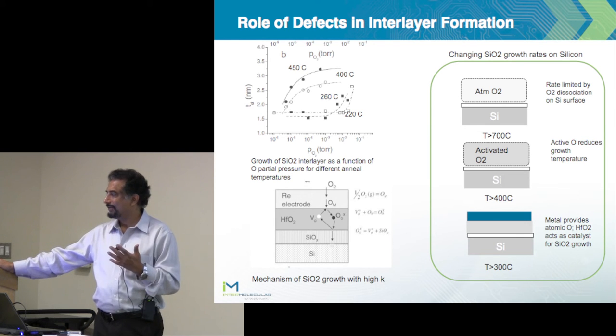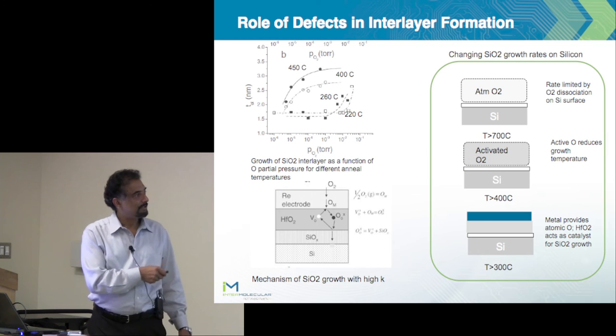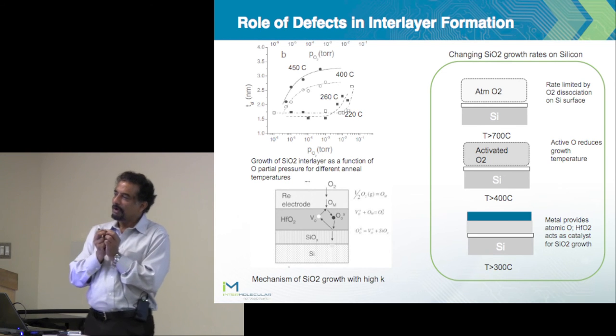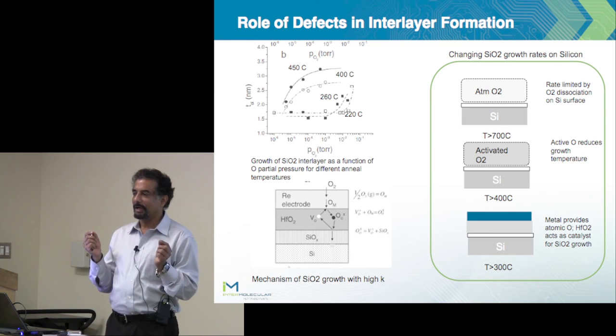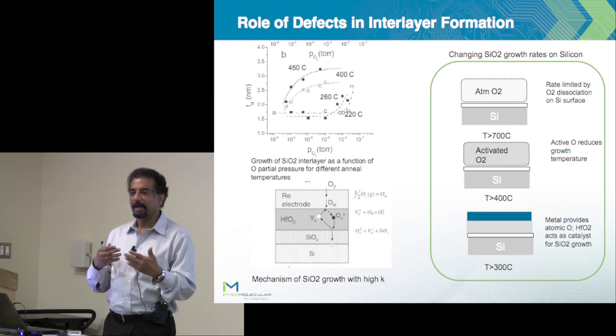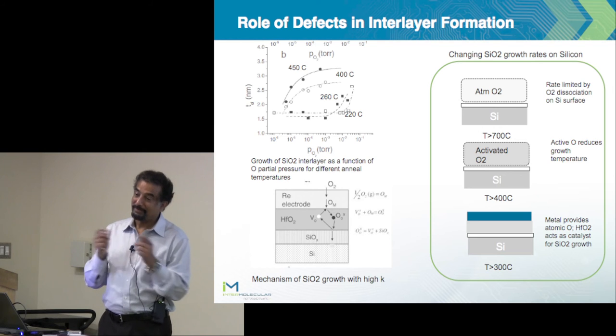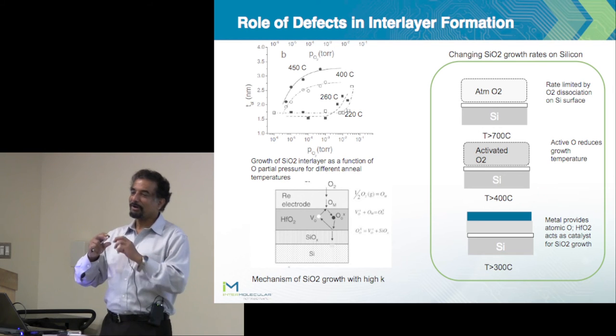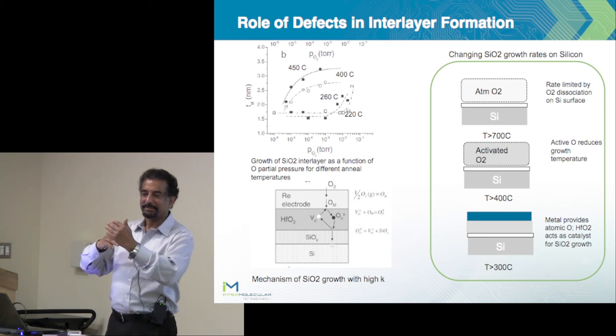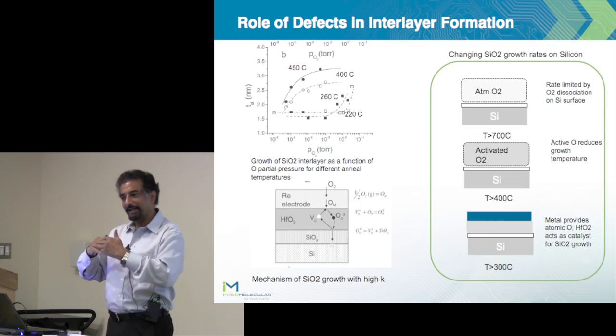In fact, the way to think about this system is that you always need some level of silicon dioxide, because you get the best mobility and you also get the best reliability. So you almost need 3 to 5 angstrom of SiO2, and you're adding the high K metal gate to add some physical thickness, but you're in effect scaling.